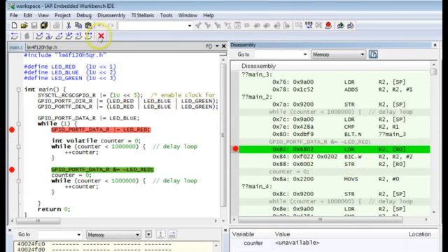This is quite remarkable because the compiler didn't literally follow your code to perform a bitwise AND with the complemented bit mask. Instead, the compiler clearly understood your intent to clear the bit and generated an even better code for it. I'd like you to remember this example because it shows you that by following established coding idioms, like the idiom for clearing a bit, you allow the compiler to understand your code at a higher level of your intent, not just the low-level operations.